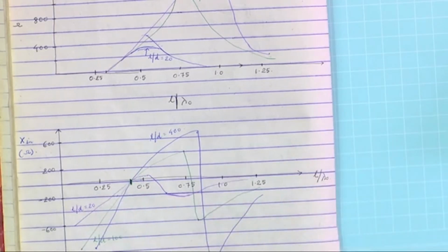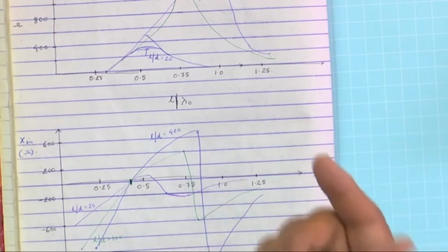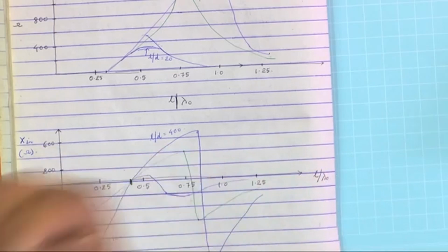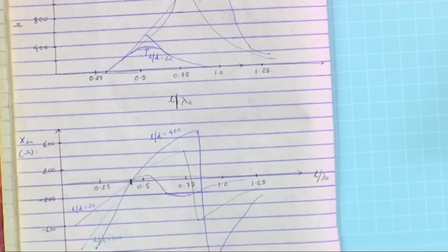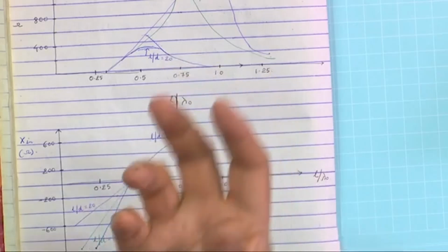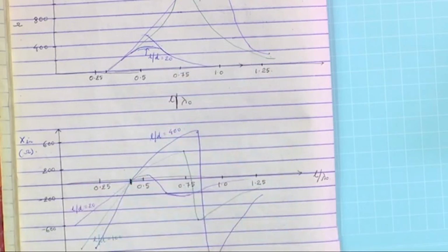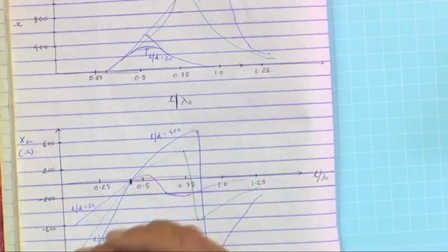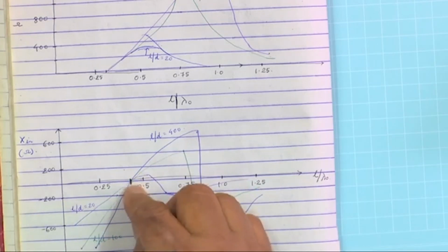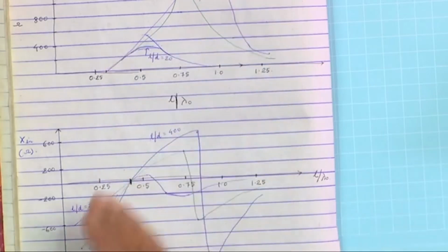In the old police jeeps, you will see that there is a coil at the bottom of the monopole. Actually, that is due to this: the coil serves mechanical stability, and it also tunes out the additional reactance at that point.